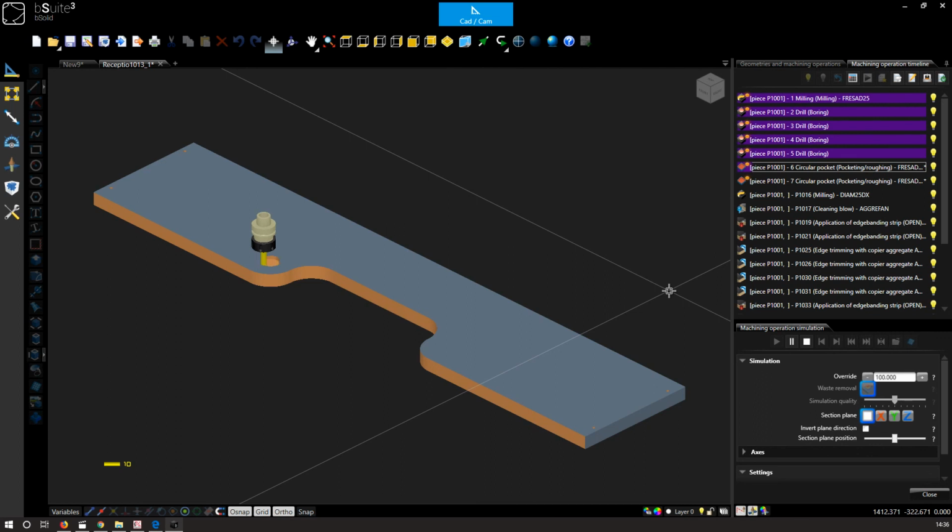Okay, and we have some drills, and then we have our pocketing. So again, we have rules that will determine how many steps the pocket needs to be completed in, and the speed, direction, lead in, lead out, all configured directly from IMOS, so that all of these settings are done automatically, and the programs can just be run within the Biesse Suite software.